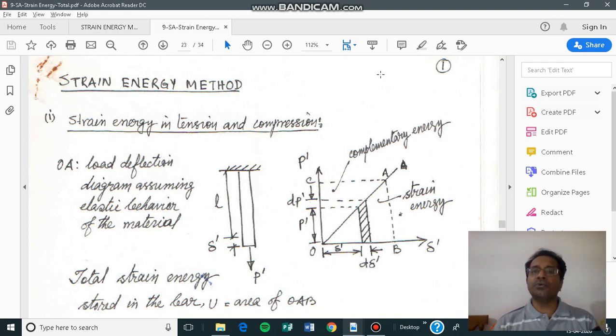Similarly, the external loads for this deformation also develop some work done. The concept is the work done due to the external load and the deformations is equal to the strain energy due to internal forces because of those same deformations. They are equal. So that concept is used to get the deformation, that is the slope and deflections.